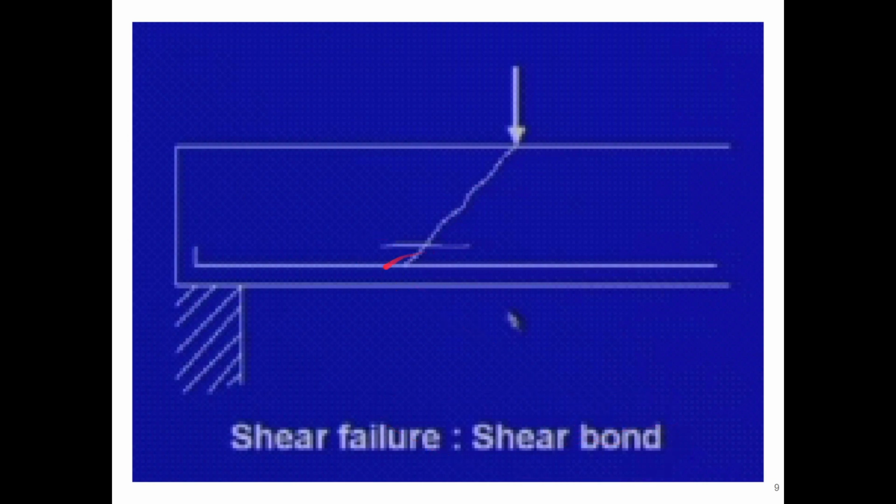Okay, so there is some shear strength provided by the rebars. The longitudinal rebars provide some shear strength, because of which the crack is not able to propagate through it. However, it is not fully capable of resisting the shear. So that's why we need another component of steel reinforcement, which is known as stirrups. So we will study that now.